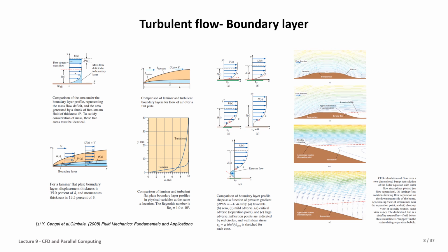When the separation happens too early, the pressure difference will be too high, and then the drag force is too high. But when we make the separation point happen later, we can reduce the drag force. In the turbulent flow, the separation happens later than in the laminar one.